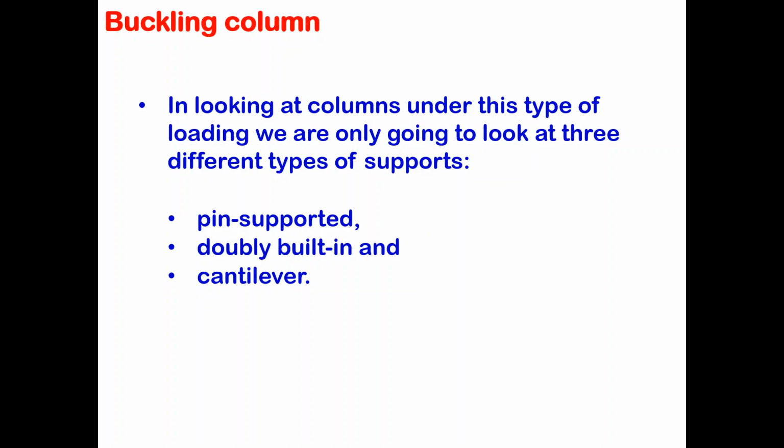Yeah, and we already have an equation that's the KL/4, but we don't have the spring stiffness there, right? We never have the spring stiffness because that is not a real spring. That was just an assumption, a hypothetical structure to help us analyze the case. So we have to look at the critical buckling from another point of view.